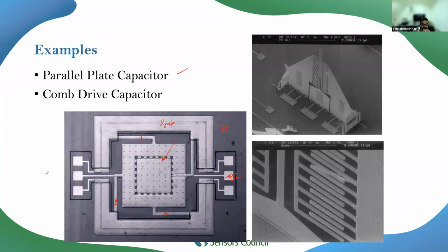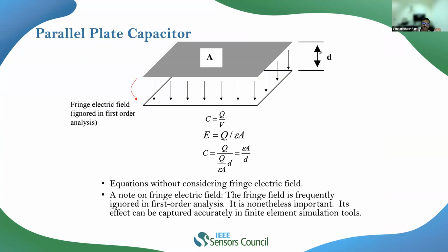And this is my substrate, these are anchored onto the substrate. And this is a proof mass, this is a perforated proof mass. On the other hand, one can even well have a comb finger configuration or comb drive capacitors. So these are basically a fixed set of comb fingers, and these are a movable set of comb fingers. One set is fixed, attached to this, and the other is a movable set of fingers attached to the proof mass.